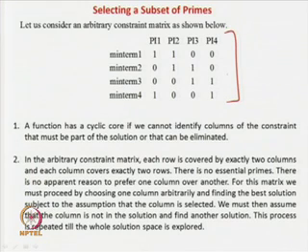So I will take an arbitrary matrix and start. You see this is an arbitrary matrix, a very special kind of arbitrary matrix which is called a cycle. In this case there is no singleton row, that means there is no row which has only a 1. See, this has 2, this has 2, this row has 2, this row has 2. That means in this case no prime implicant is an essential prime implicant, because there is no row with a single one, no row having a min term which is available nowhere else.